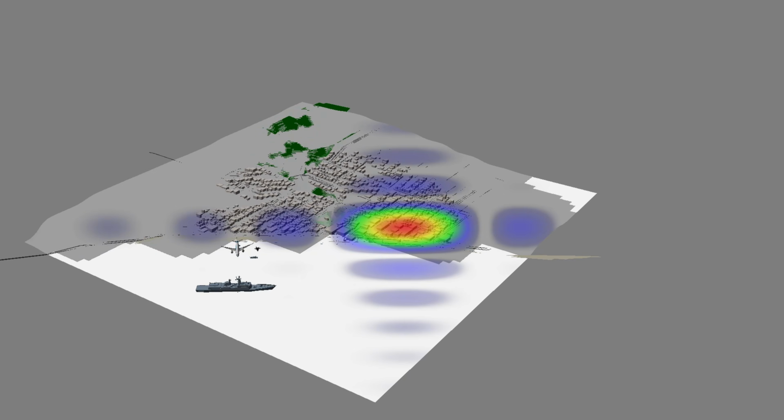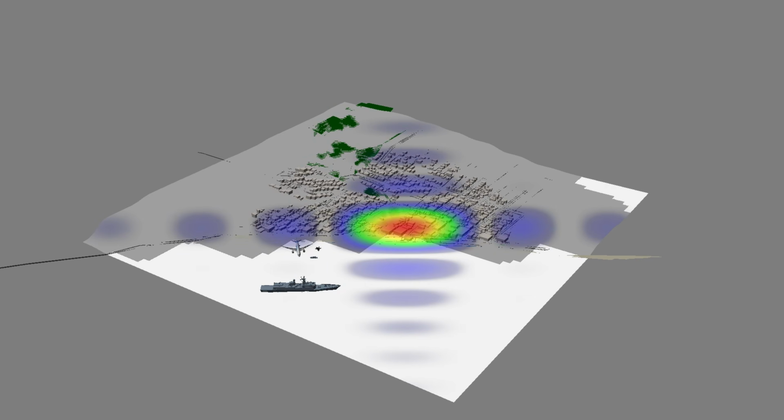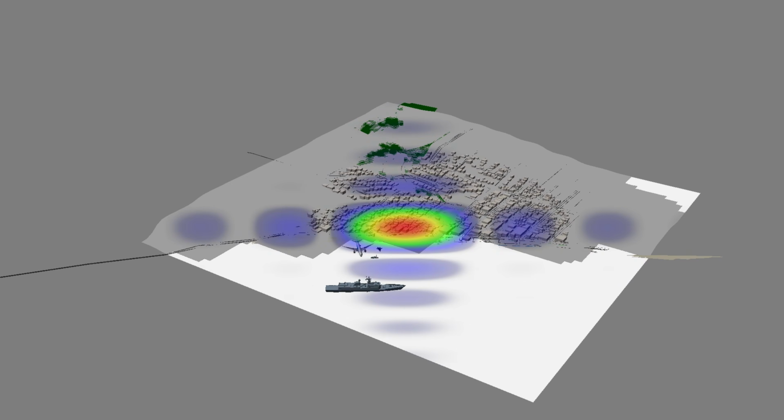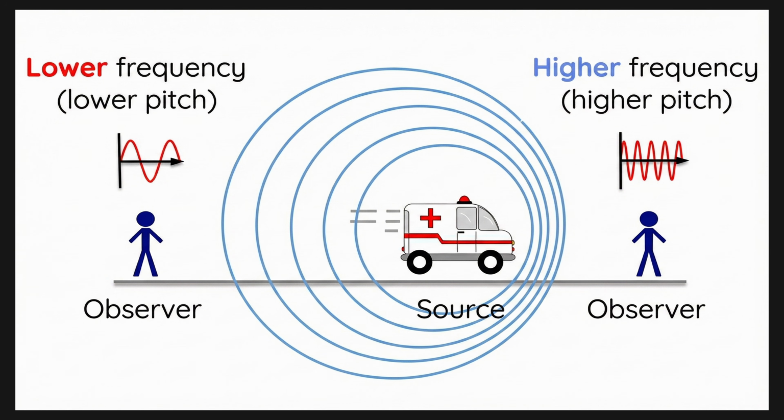We will start by showing a synthetic aperture formed by an aircraft in Stripmap mode. Here the SAR antenna will move across a scene, and the size of the synthetic aperture will be the physical width of the antenna beam projected onto the ground. As the radar moves across the scene, a Doppler effect is produced. Return signals from objects the radar moves towards are shifted to higher frequencies, and the signals from objects the radar moves away from are shifted to lower frequencies. Therefore, the synthetic aperture is formed in the direction of motion, which is called the azimuth or cross-range axis.